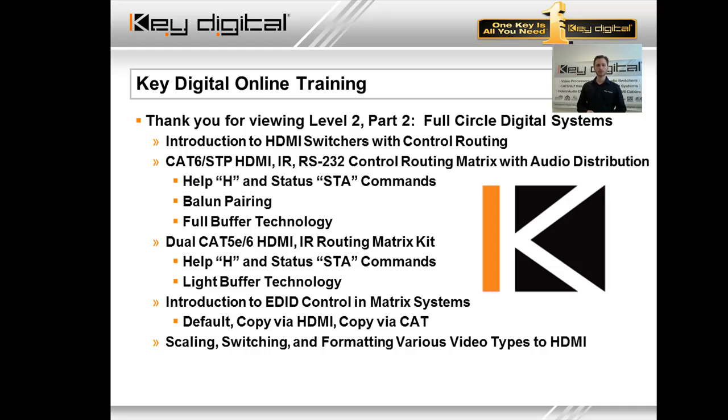We talked about the products with the Cat 6 shielded. Those are the Hercules and Digital IQ. Why are they Cat 6 shielded requirements? Because it is a single Cat 6 cable only. And if you just have a single line, and you get any electrical interference or grounding related issues, it's likely to affect the entire transmission, which is not a pretty picture. Pardon the pun. We discussed help and status commands. We took the whole nickel tour on those, didn't we?